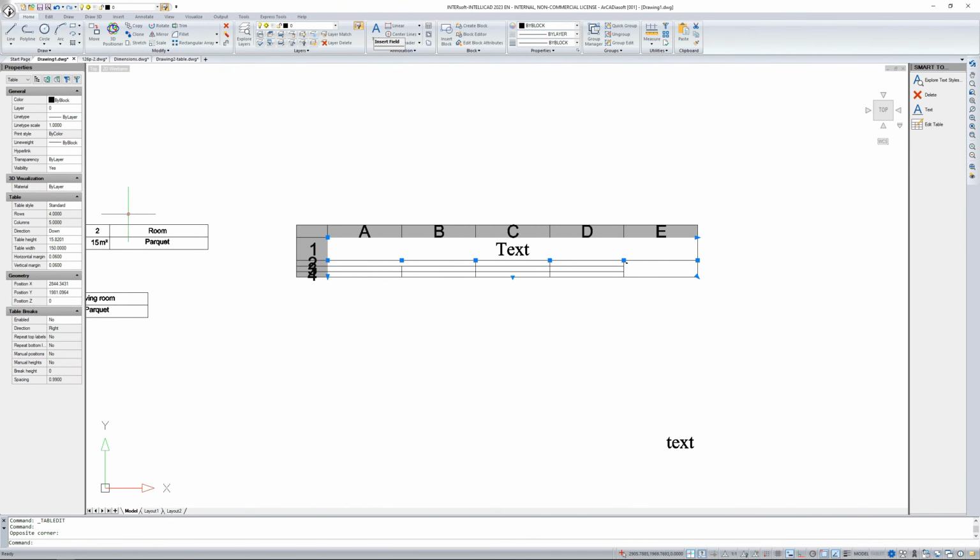Pen thicknesses can be defined by layer. And here, after selecting the table, I have these elements to be modified. So line type, thickness scale, and thickness. By default, it is of course the same as in the layer.